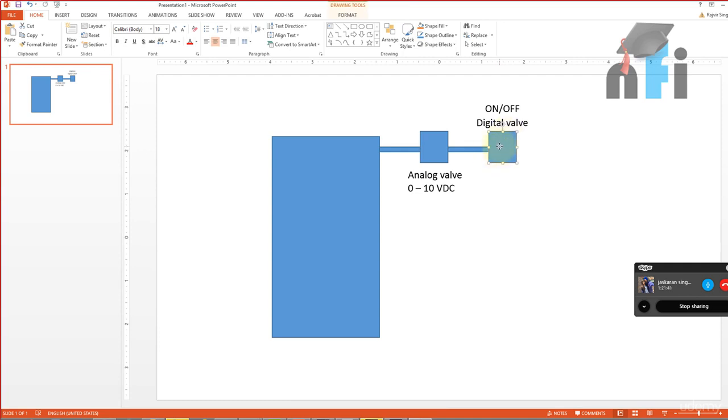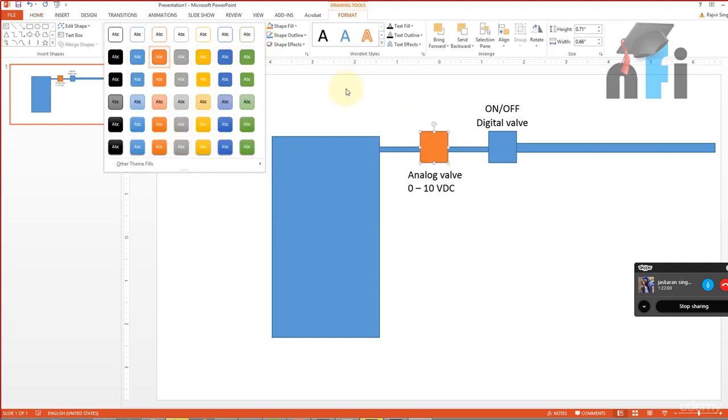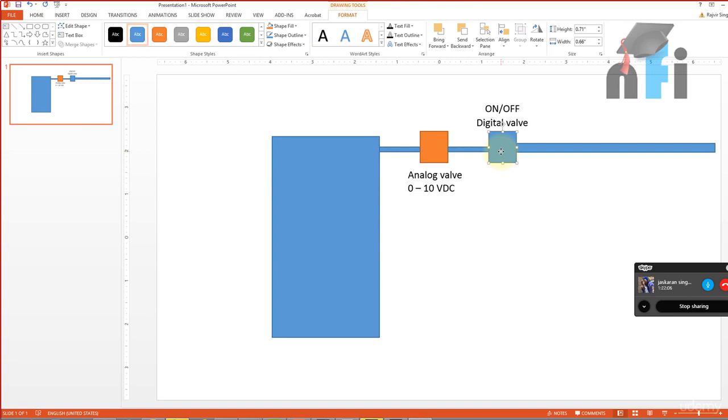If this valve goes off, then there will be no filling, even if this is on, because the water is coming from here. This is the main supply of water. So first we have a digital valve, we turn it on initially, then we do the auto mode. If auto mode fails, if this valve is failed and not working anymore, then this will be off based on the level here. So when this goes off, there will be no filling. Are you getting me?